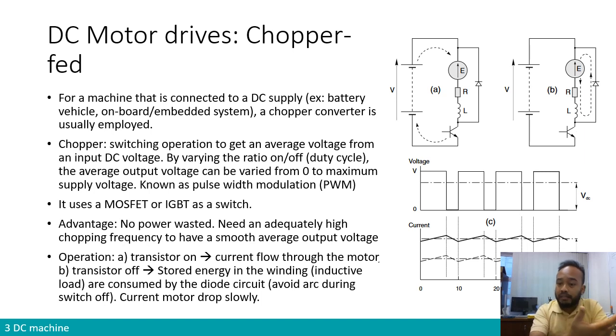We have a rectification first. The rectification is done using the usual power diode, not thyristor. But then, once it is rectified, we add behind it a chopper or PWM driver circuit. So we have rectification using diodes plus a chopper using PWM, using a transistor, to rectify and then adjust or change the level of the average output voltage. So it can be a combination of both.